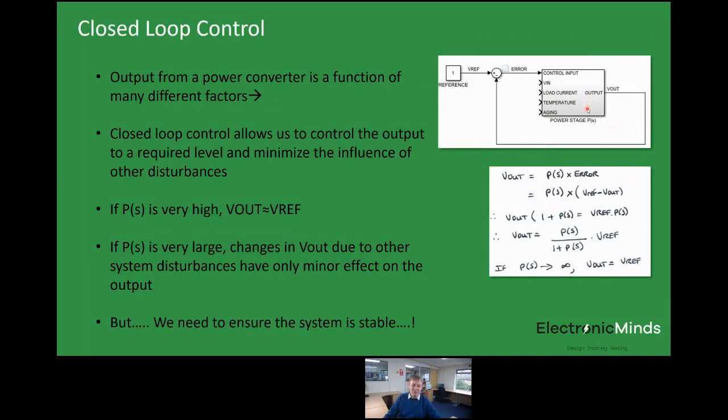You need to make sure the system is stable, and there are certain requirements on the feedback design that if you make this gain too high or it has the wrong gain and phase characteristics, then if you were to close the loop on it, it would actually oscillate, it would become unstable. And effectively designing your analog control system is the process of designing that model to be stable and give you the characteristics you want. So we'll launch question 1 at that point, please, Jose.